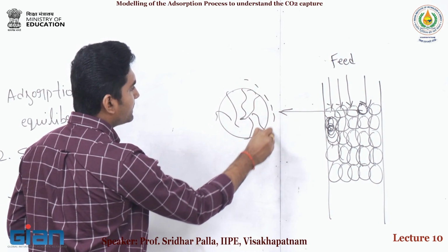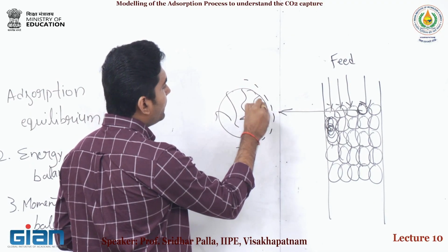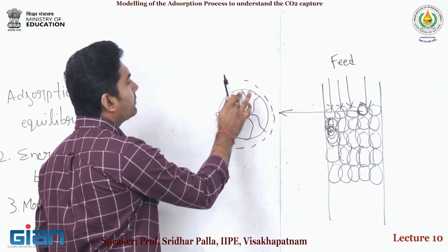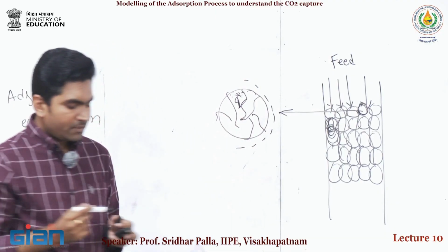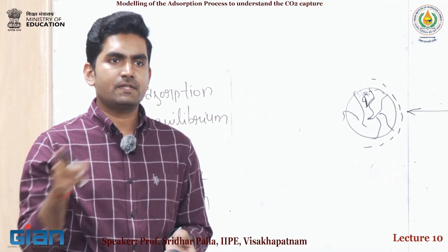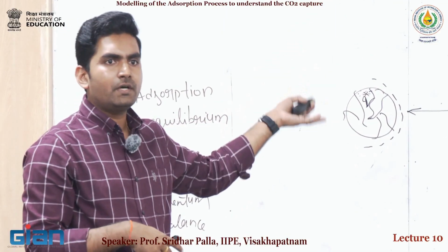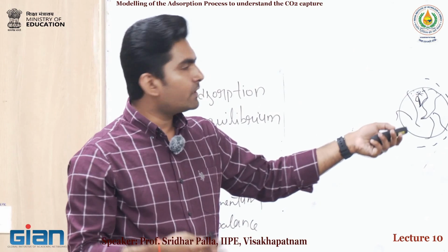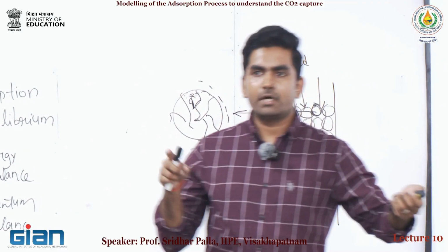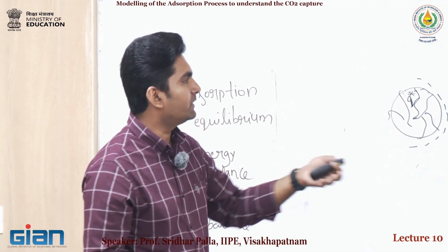Before reaching the pellet, there is a film resistance, and also there is gas that is adsorbed on the surface, at equilibria. The local mass equilibria assumes that there isn't any film resistance or diffusional resistance. I am assuming that ∂q̄/∂t is directly equal to the adsorption equilibria amount, but that is not exactly correct for the real case. We will see how ∂q̄i/∂t is equal to, and also we will consider multiple diffusional and film resistances in between.